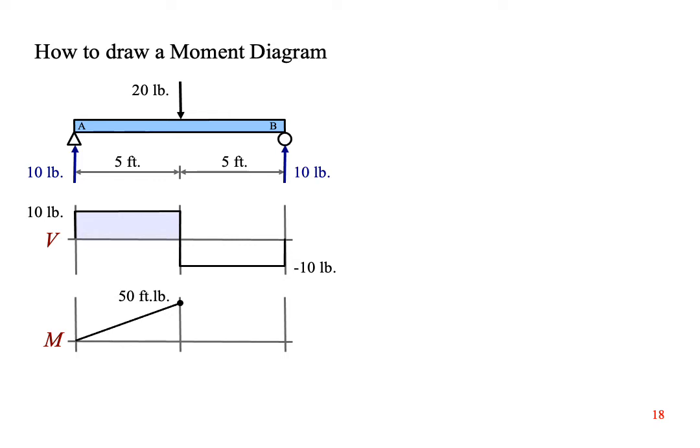The rest of the shear diagram is negative, so we subtract the negative area, which takes us back to a moment of 0, which makes sense because it's a roller support. There can't be any moment remaining in the beam at a roller support. Shade in the area of the moment diagram. Make sure you've marked the values where the moment diagram changes direction, and you're done.